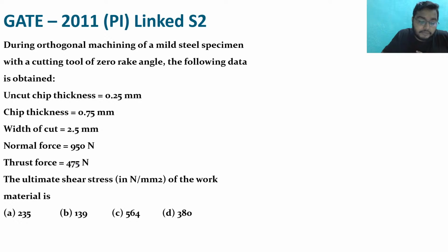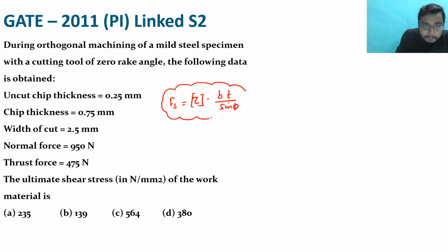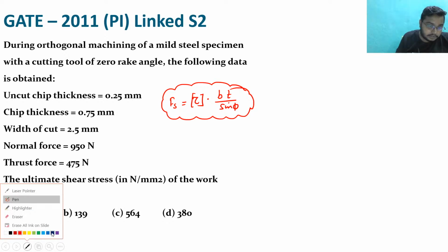Ultimate shear stress you have to find, right? You already know that shear force is nothing but ultimate shear stress into bt by sine phi. We have discussed this formula, okay? Use this formula to find ultimate shear stress, right? This is your ultimate shear stress.